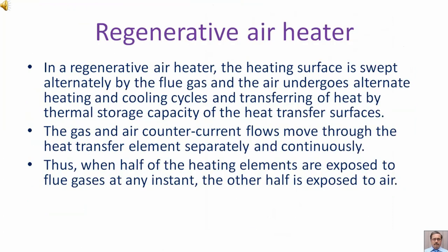Regenerative air heater. In a regenerative air heater, the heating surface is swept alternately by the flue gas and the air, undergoing alternate heating and cooling cycles and transferring heat by thermal storage capacity of the heat transfer surfaces.